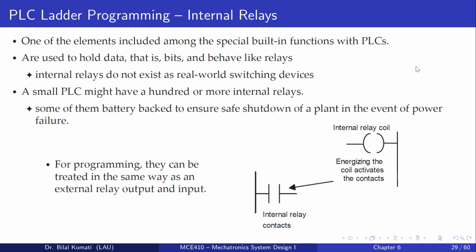So we're talking about PLC programming using ladder programming. Now we have reached the internal relays. The internal relays are one of the elements included among the special built-in functions with PLCs. They are used to hold data, that is bits, and behave like normal relays. So they are very similar to normal relays.